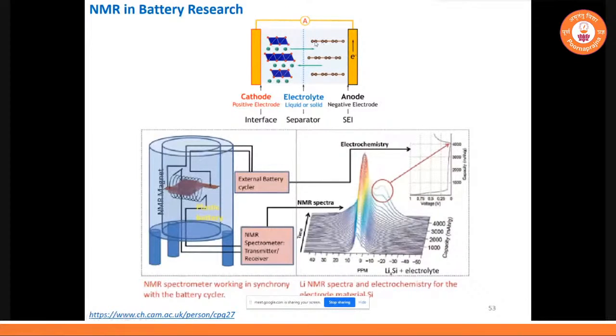Now we know that usually they are using liquid electrolytes, but they are very volatile, and we have recent incidents of batteries catching fire. So now there is again a push towards safer electrolytes. People are thinking about solid electrolytes in a lithium ion battery. But the problem is that the lithium conductivity we are achieving in liquid electrolytes cannot be matched by solids, because lithium movement will be restricted there. So now people are pumping money to get a safer electrolyte, to understand the lithium dynamics in a variety of materials.